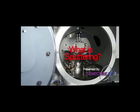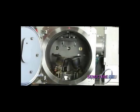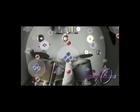So exactly how does the sputtering process work? First, your coating materials are placed on a magnetron in a solid form called a target. For highly pure coatings, you need a clean environment with only materials of your choosing. This is why the chamber is evacuated, to remove almost every molecule from the chamber. Then, the chamber is backfilled with a process gas. Process gas species are chosen based on the type of material to be deposited. Common process gases include argon, oxygen, and nitrogen.